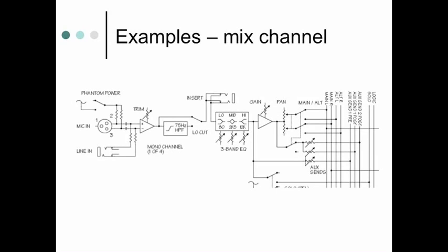All of those levels, except from the amplifier to your speakers, is line level, and except from your microphone to your mic preamp, because the microphone's quieter, so the mic preamp is a special amplifier to bring it up to the normal operating level in the studio, which is line level. And from your amplifier to your speakers has to get much more power to drive the speakers to move the air. But everything else between those two points is operating at line level, which is your normal or nominal operating level in the studio, and that helps you transfer signals from one piece of gear to the next.